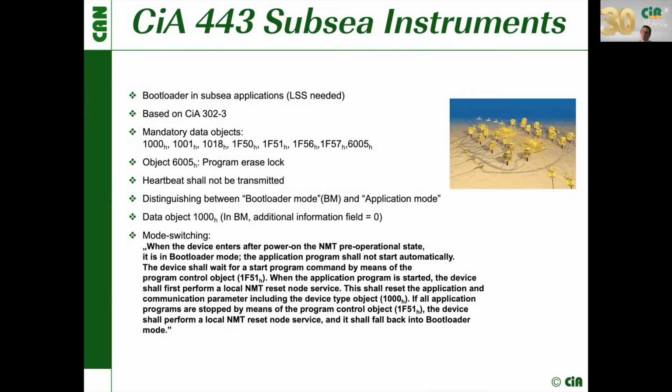Nevertheless, both of them, CiA 454 and CiA 417, if available, start their application program immediately. The other way around, CiA 443, the device profile for subsea instruments, is working. Here the devices, first of all, start in the bootloader mode. And in the bootloader mode, the host controller has to evaluate whether the correct application programs are provided and which one shall be started.